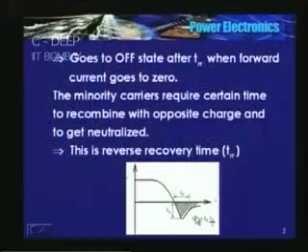So, reverse recovery time and reverse recovery charge are two important parameters. Why are they important? See, even though the current has become 0, the diode continues to conduct and goes to off state only after TRR.